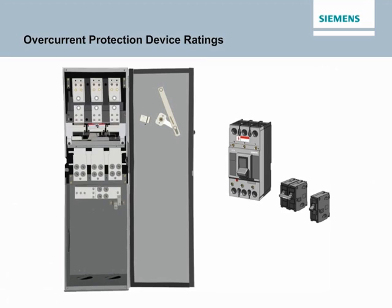Conductors are also rated for how much current they can carry continuously without exceeding their temperature rating. This is commonly referred to as the conductor's ampacity. In general, the ampere rating of a circuit breaker or fusible switch and the ampacity of the associated conductors must be at least equal to the sum of any non-continuous load current plus 125% of the continuous load current.